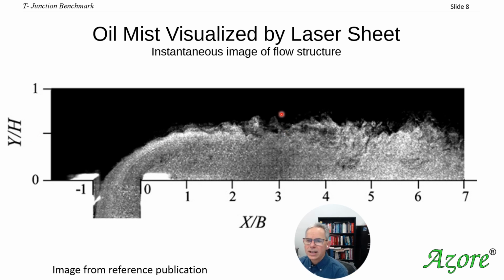One thing to notice right here is that because we have these turbulent flow structures, it's very irregular, and you can imagine this changing all the time. Here's our cold air, but look right down here, you can see where the turbulence has really transported a portion of this cold air all the way down here. And this is probably moving. So the turbulence is playing a fairly major role in mixing these two together, and we're going to look at that some more. It's good to have a good understanding of how turbulence really affects this mixing process.